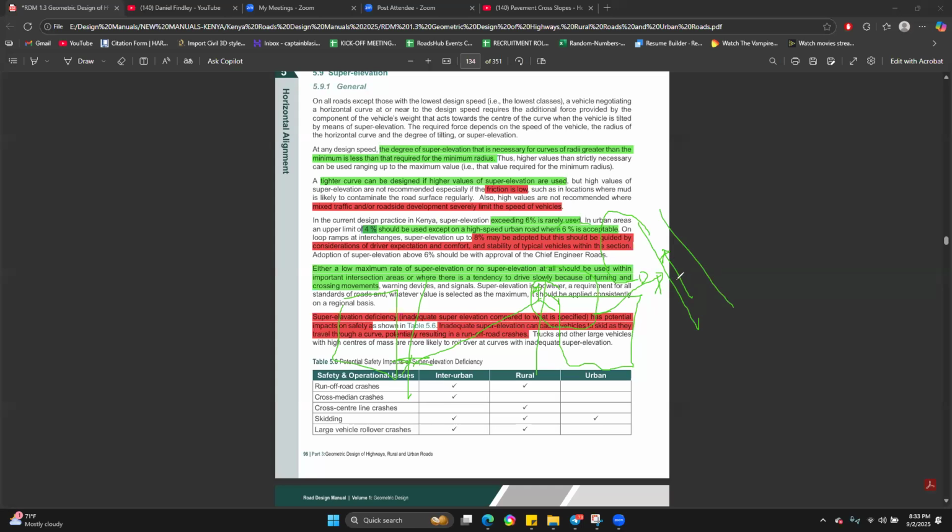Remember the clearance from the bottom of the bridge to the FRL or the blacktop of the underpass road should be not less than, I think, 5.8 meters. So you can imagine you're driving from this top here, that's above maybe 6.5 meters, all the way down there. So you need an Emax of actually around 8%, not more than 8% though, but not less than 6% for you to navigate this ramp successfully, right?